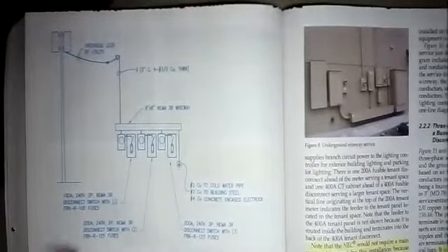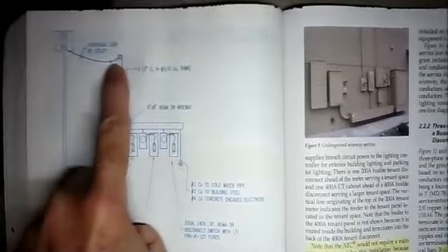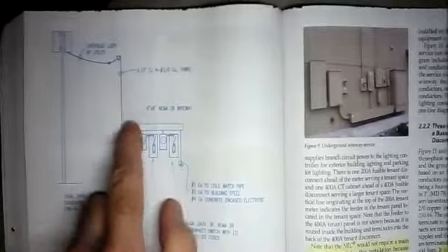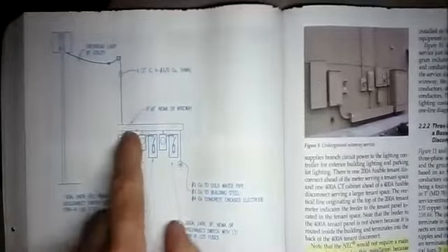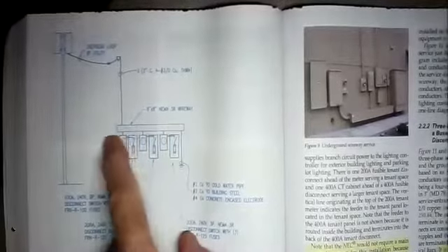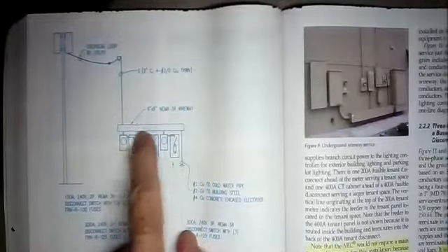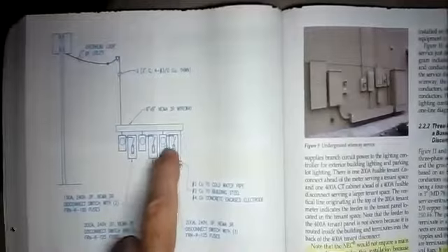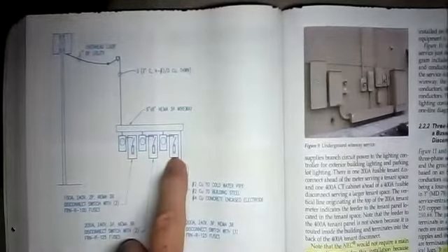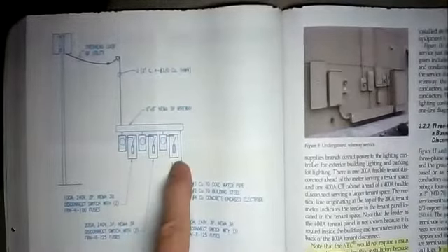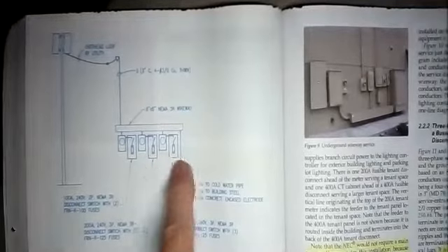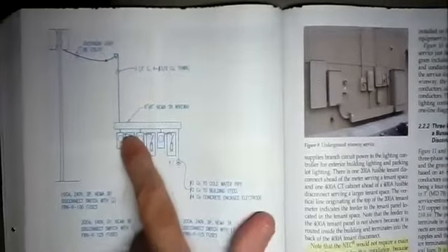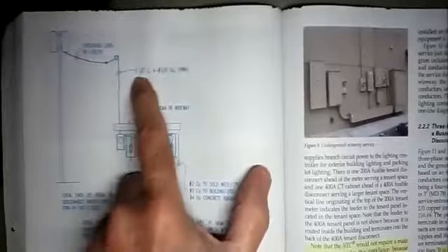Now we get into a couple of different examples. Here's a service drop coming to a weatherhead, and there's your riser coming to a trough. This is a wireway. Off of that wireway, they will bring the metering equipment and the main disconnects for 3 slot stores. So this is called a one-line diagram. This one line represents